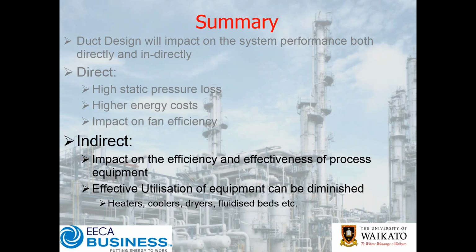I've on numerous occasions come across 1,000, 1,500, 2,000 pascals drop across some innocuous ductwork. That tells you you've got a problem in terms of troubleshooting. Now, you might need to dig a little deeper to figure out what's going on, but if you're more than 100, 150, 200 pascals tops on some decent ductwork, you've generally got something going on that you need to be worried about. And it's very, very easy to have those sorts of losses, but as we've demonstrated with a couple of those examples today, easily rectifiable.